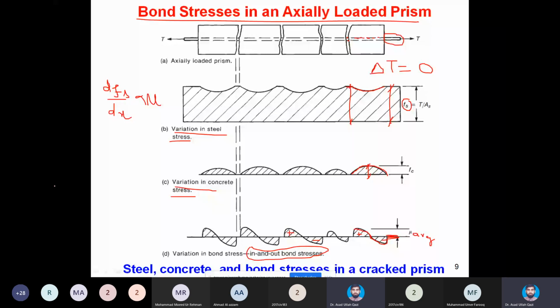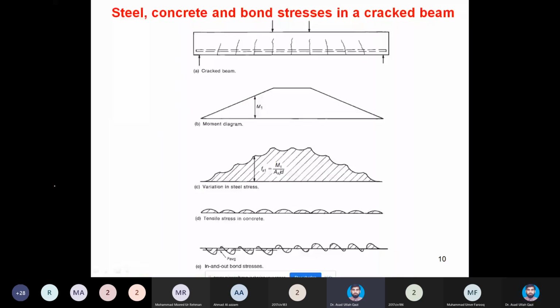Now, a little more discussion on another beam, which is subjected to two-point loads. Again this beam has simply supported end conditions, a single span, but the only difference is it has a pure bending zone, the middle third. In exactly this picture, they are not actually equal one-third areas. The two-point loads are closely spaced, and we have more span in which moment and shear both are present. But actually this middle area is free from shear. We will have a shear force diagram like this, positive and then negative, but there will not be any shear force here, zero in this region.